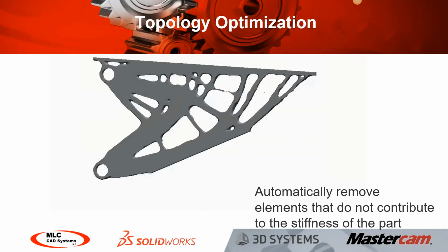As you can see, we're getting a non-parametric optimization of our part. The software will organically remove the mass based on where and how the loads are transferred through the part. So elements that don't contribute significantly to the overall stiffness of the part are getting removed.